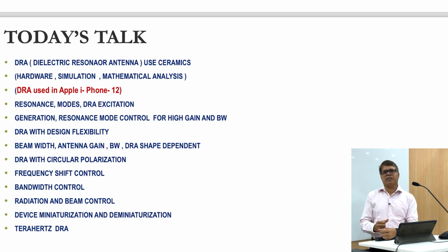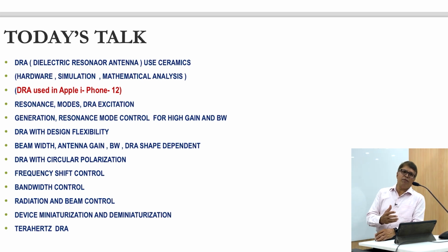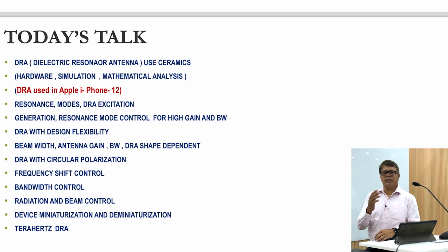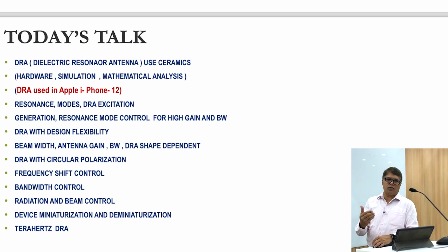So in 5G we have different bands, from sub 6 gigahertz to 77 gigahertz and 95 gigahertz. These are millimetric wave bands which are very useful for lidar, radar and different 5G communication applications. Beyond 95 gigahertz we have some specific terahertz frequencies where we can design very compact antennas or compact DRAs. Now, why should we go for terahertz or the millimetric wave band?